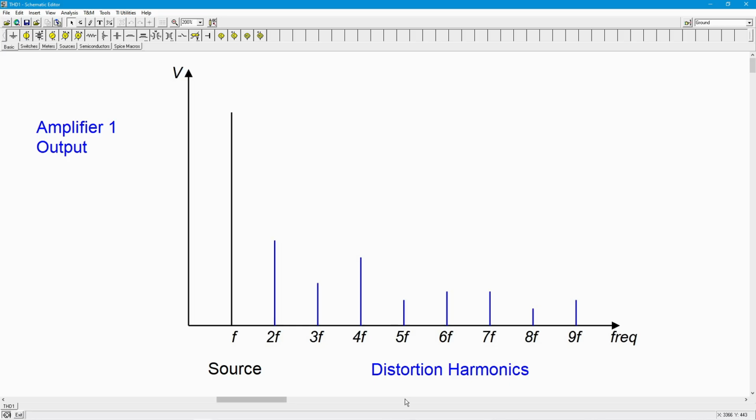Again, I'm going to assume that these two things have the same THD total, right? When we sum up all of this stuff compared to the whole thing, the total harmonic distortion. So here's a second amplifier. Now I've got these in red. Notice that the odd harmonics are stronger here. But again, the idea is that when you sum all of this stuff up, you get the same value as you do over here when you sum up all these.